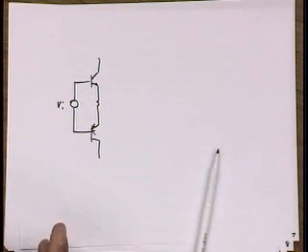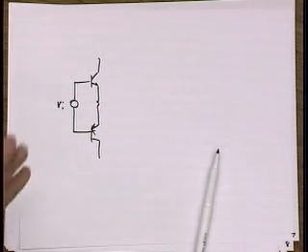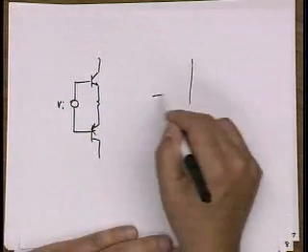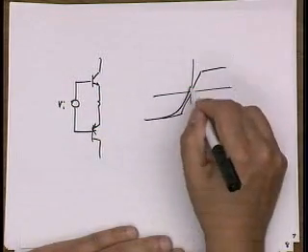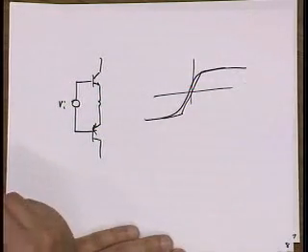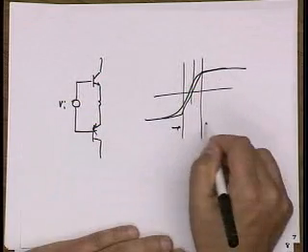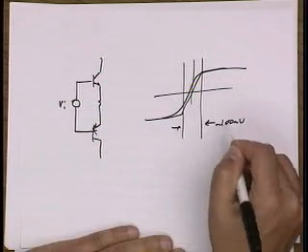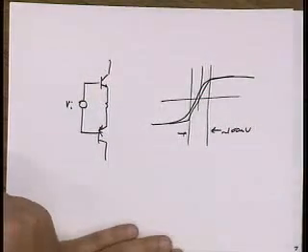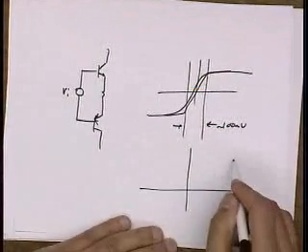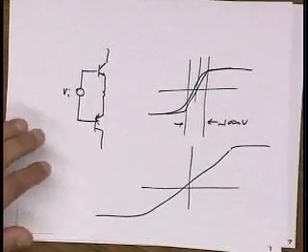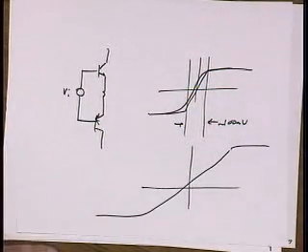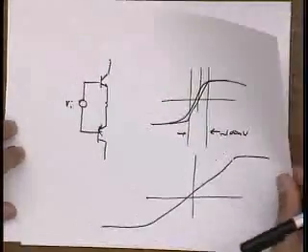It's just a few kT over q. So if you look at the transfer characteristic of a diff pair, it's very sharp, right? It's this hyperbolic tan characteristic, and it's very sharp. So over hundreds of millivolts, it saturates. For MOS, it's kind of like a square root function, so it's a much larger input range. All right, it's a good question.